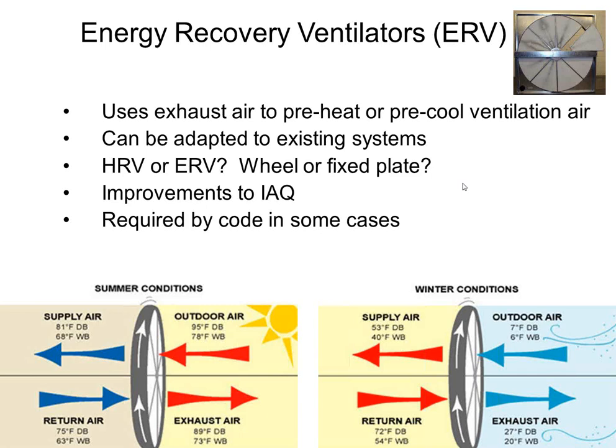The only time we don't use an ERV and we recommend an HRV is when the indoor humidity is expected to be regularly worse than the outdoor humidity, right? So that basically means locker rooms that have showers, a greenhouse where they're spraying water on plants, something like that where moisture is being introduced, some kind of giant lobby that has some kind of water fixture, fountain type thing, something like that, then we might not want to recover the moisture in those cases.